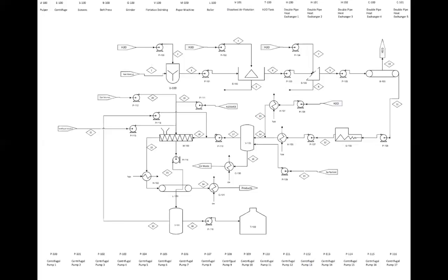The surplus sludge from the dissolved air flotation tank gets recycled back into the paper machine. And once this process is done, the material is heated up to 120 degrees Celsius. It goes through a roller where it is pressed into flat sheets and then cooled back down to room temperature. And then our end result is solid paper for our products.